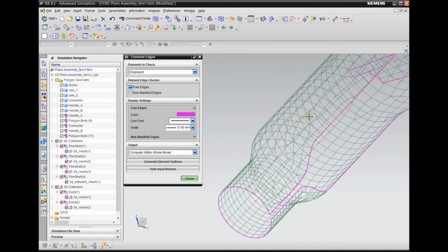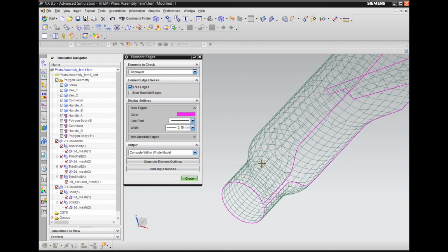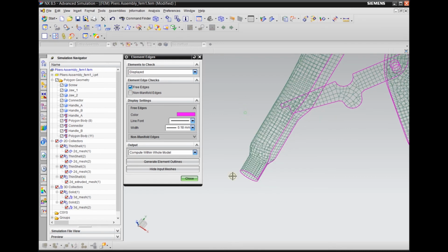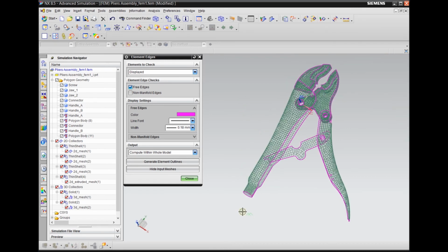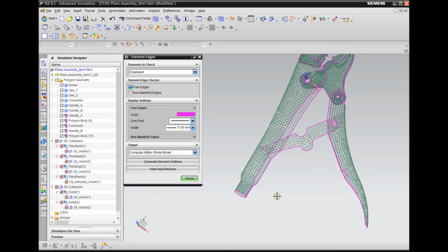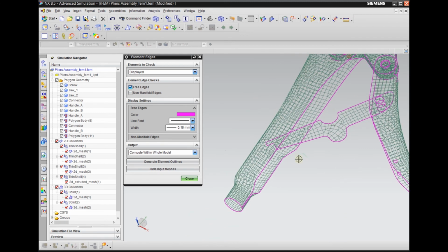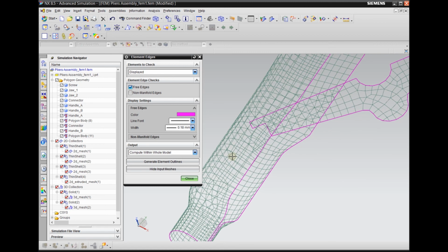So you see here, the 2D mesh and the extruded 2D mesh, they don't have a free edge between them. So that means there's no duplicate nodes. They're one piece. I don't know if Dr. Zada has emphasized the free edge. The free edge means you have elements on one side of your node, but there's no element on the other side.